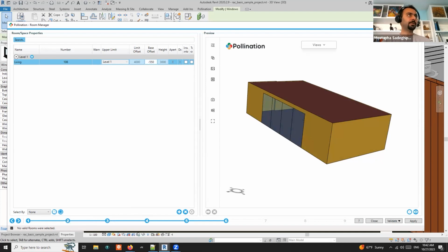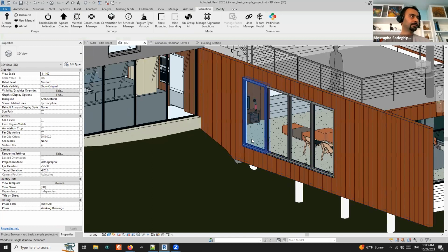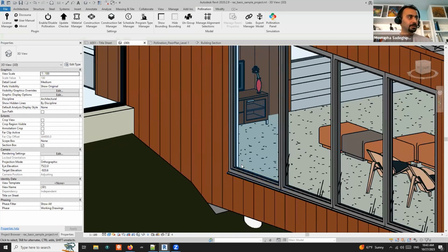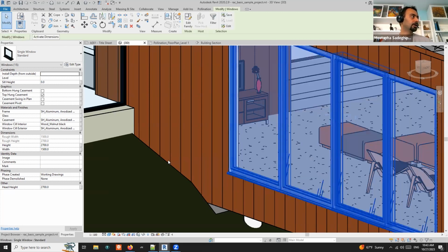So what's really happening here is if you go here and check this Revit model, do you see even like the color of glass for this one is slightly different from the color of glass for the other ones? That's why now if I select this and right click and select all instances in the entire project, you'll see what happens is this glass material is not set the same for all the instances in the model.